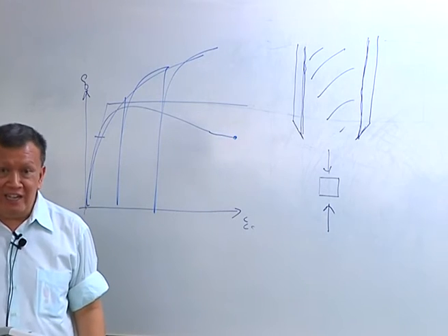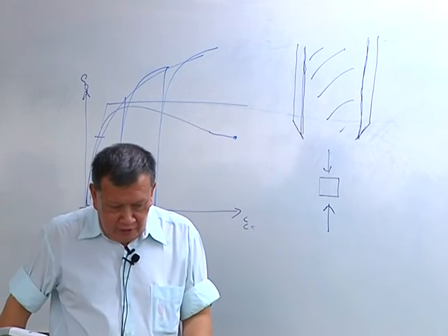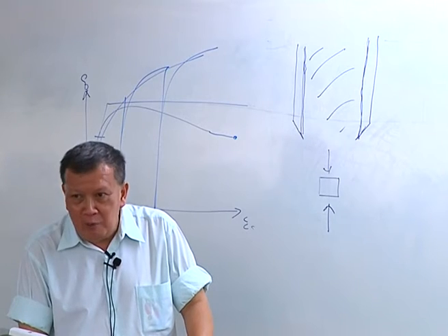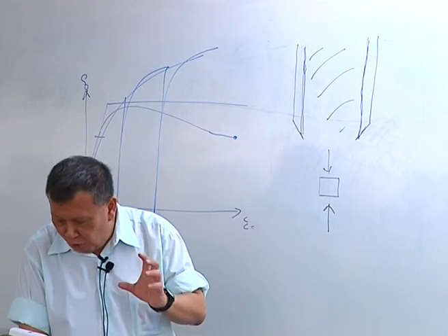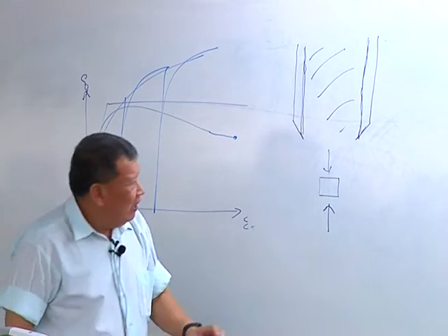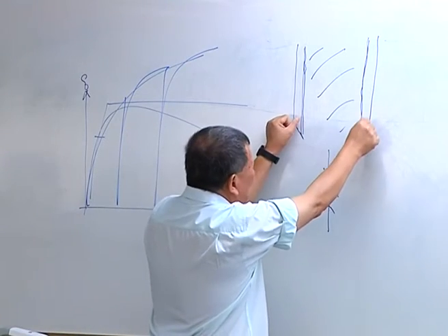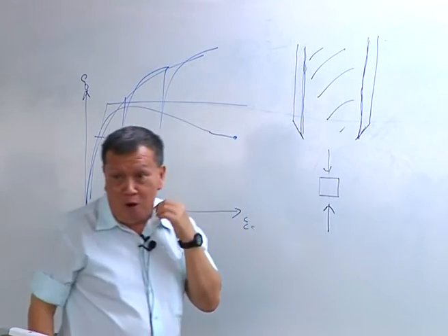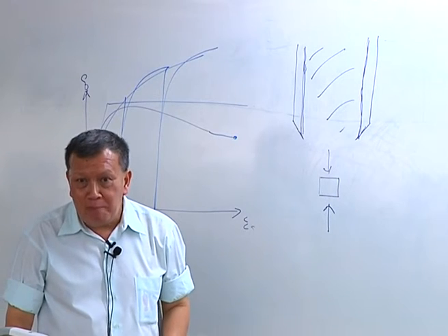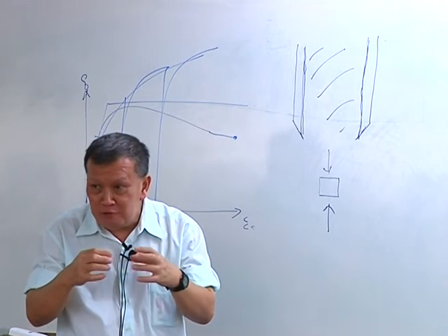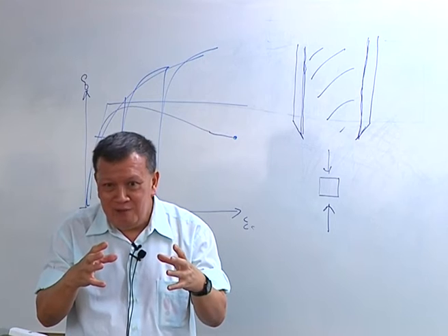slide in easily. The weakness, the drawback with that is this: you end up with a sample with a small gap between the sample and the wall of the sampling tube. So over a period of time, the sample will lose effective stress. It will start to swell. It will lose effective stress.